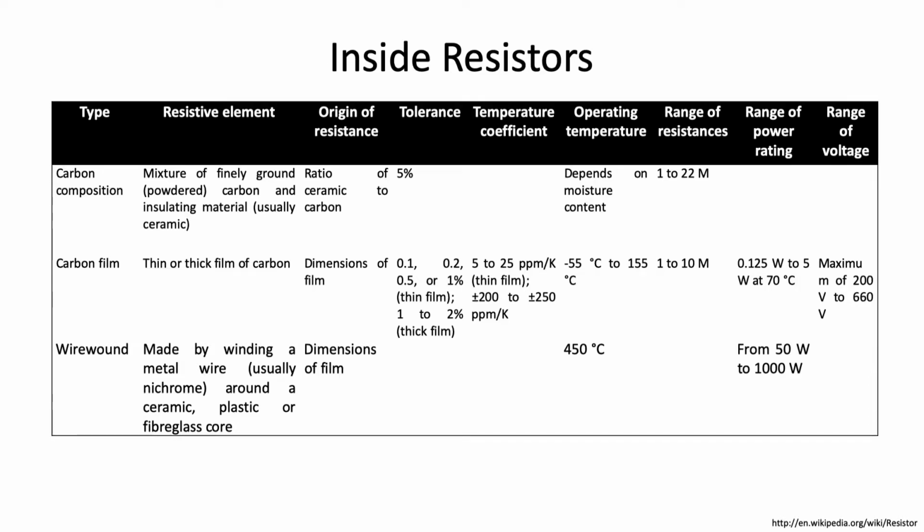The most common material used in resistors is carbon, but you can also use metal film type. Carbon-based resistors are easiest to manufacture and are cheaper. Metal-based and film-type resistors are a little bit more expensive. These are typically used for applications requiring less noise, better thermal stability, and those that work better at higher temperatures